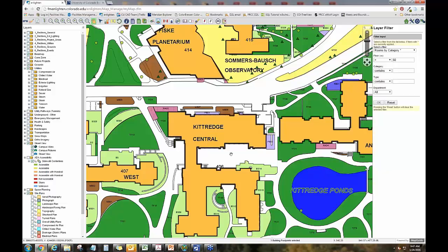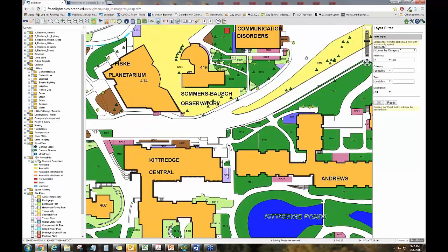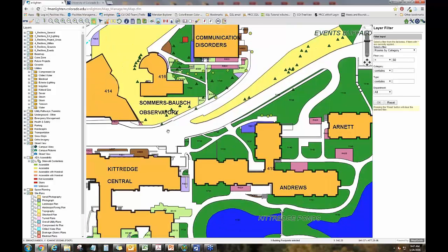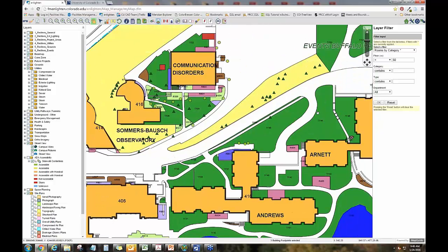And you can see with our tree data that we have trees on the north side of the road here, but we don't have any trees on the south side, or very few. That's because that's sort of the edge of our survey. The grounds crews have been going out with GPS equipment with a laser rangefinder and capturing data on all of our trees. For that, typically we set up with a tripod, on the sidewalk usually, or in the dirt. You'd want to try not to be on the north side of buildings, and this is not a great spot for that, which is probably why we don't have a lot of tree data in here.